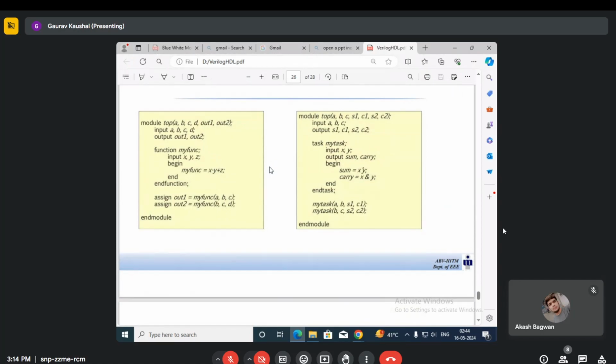So this is an example of it. Please see here, because tomorrow you need to understand what it is. Please remember that you will find the module written in your program. You will find one entity name using an identifier. There will be some input and output ports. You define the input and output ports and perform the operation as per your requirement. You may use a wire, and you may use a register if it is required.